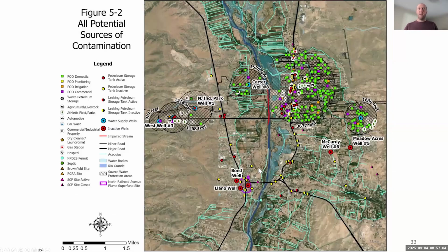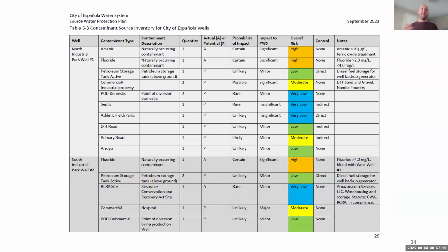You can do this for the whole community, and then you can get a strategy for what we need to focus on. Do we need to retire any wells or not use them because there's too much contamination, like this one down here that we talked about earlier, by this big plume? For each of these sources, you can analyze them for specific threats, whether they're naturally occurring, like this well, where there's potential arsenic contamination, which is naturally occurring in this area.